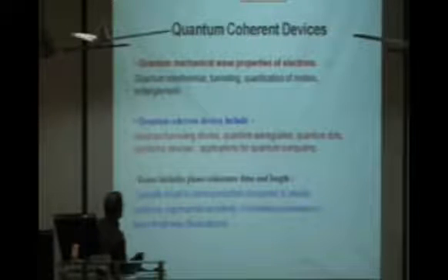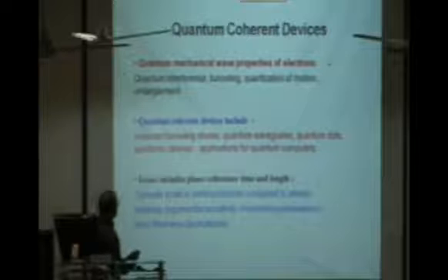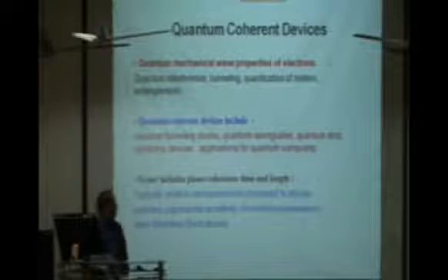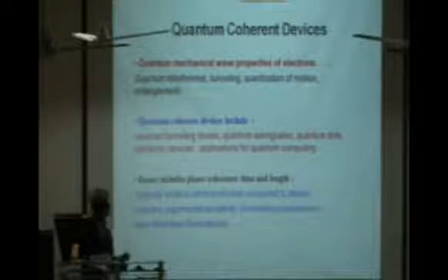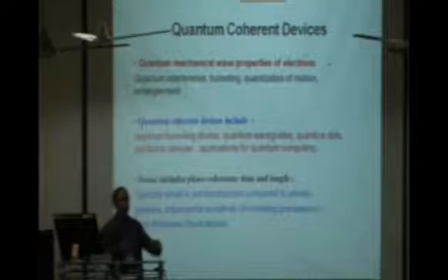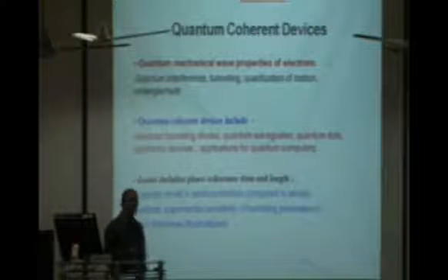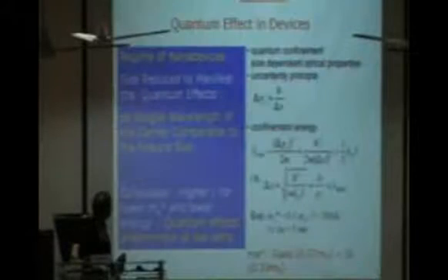Some quantum dot based devices, or some spin based devices that we typically get on spintronic materials. Of course, the challenge is that you have to have a very high coherence length or high coherence time. Unfortunately, in most semiconductors, this coherence length and time is very, very small. That is a big issue. For tunneling devices, there is always a fluctuation of the thickness, and the tunneling probability is exponentially dependent on the tunneling thickness. So it's very difficult to get all quantum dots of the same size or all tunneling barriers of the same width. That creates a lot of problems in making these device structures.